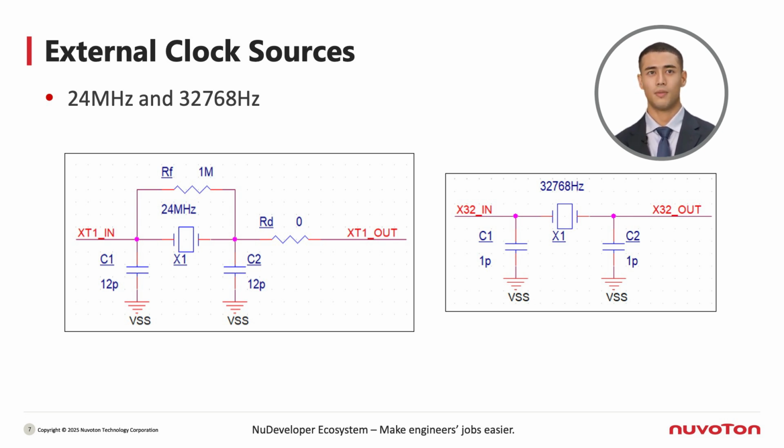When designing the schematic, pay attention to clock frequency, RF parameters, and CL parameters, etc. During layout, it is important to achieve rational placement, proximity to the chip pins, short traces, avoiding layer changes, and minimizing interference from other components.